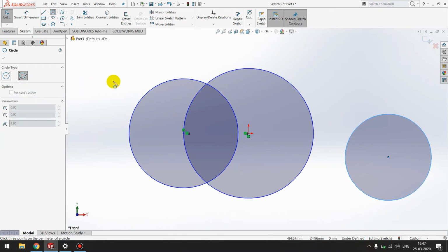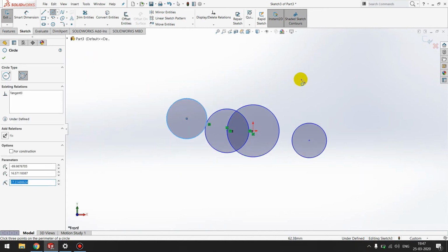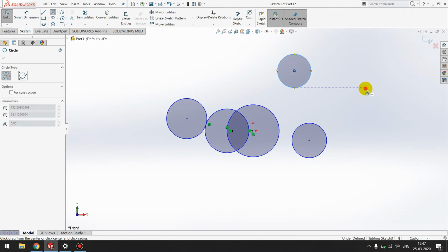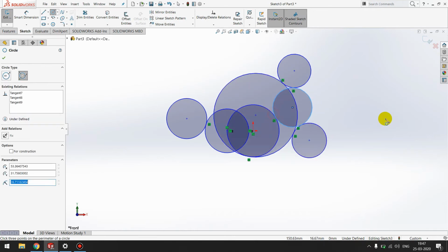Click on the perimeter based circle, and like graphically it is shown over here, click on the first point, second point, and third point. So let's say I have three circles in the space right now, and I want to draw a circle which is tangential to all those circles. So I can select perimeter based circle. Okay, I'll select this, I'll select this circle, I'll select this circle.